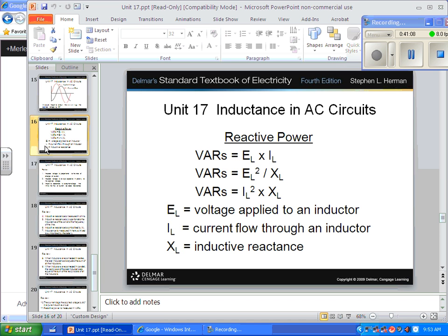Okay? So, let me finish explaining. You have apparent power, that's what you're putting in. You've got some true power of the work really getting done. Let's say it's 70%. Okay? So what's 70% of 1,200? 800 something? 840? Something like that. Okay? So you could be getting 840 watts of actual work coming out of that motor, right? About.